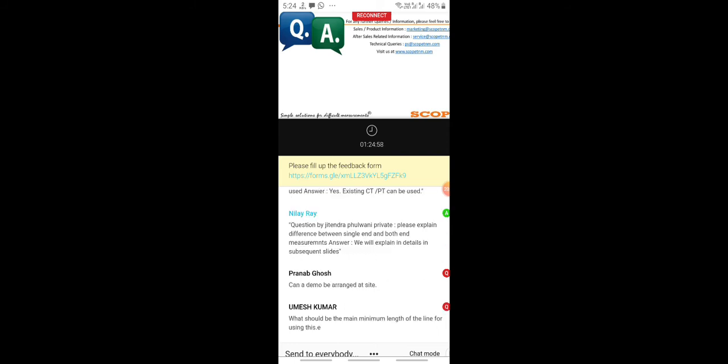So let's say, because the substations are far away, that when this particular thing happened, suppose a fault occurred at one end of the substation, and your GPS did not work for any hypothetical reason, the waves will be captured there. So you mean to say that GPS will be available at either end, and whatever the last signal we have received, based on that it will be synced.